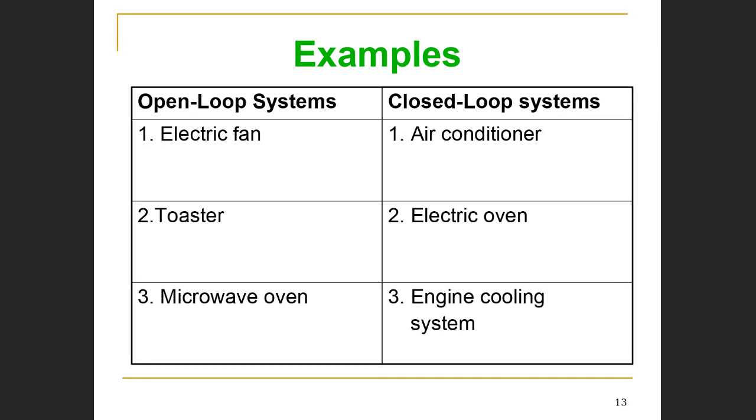Next, the electric toaster. It's designed to change the shade of bread, and by so doing, persons will experience a different texture to their bread. But essentially, the toaster is going to change the color of the bread. As far as I'm concerned, I've not yet seen a toaster with any sensor to actually observe the color of the bread and then do something. So it's open loop. If you take one type of bread with the same setting, you'll end up with different results.